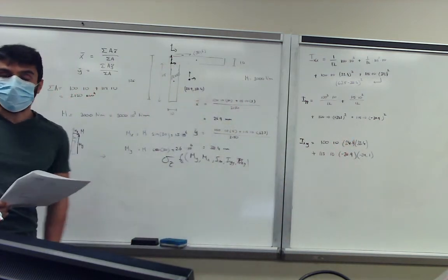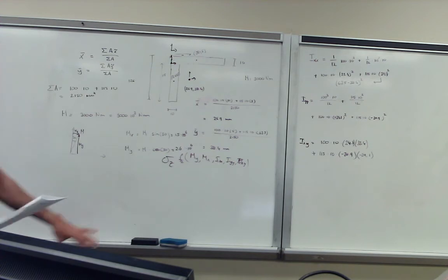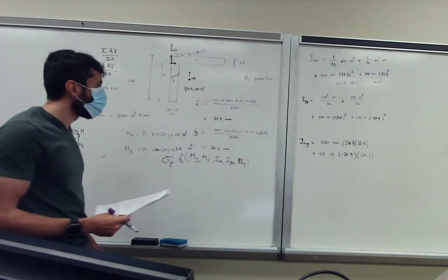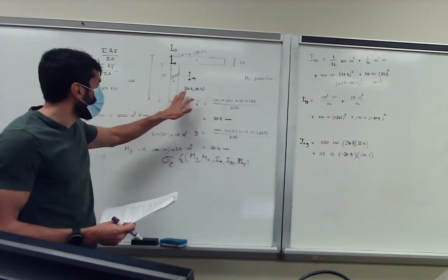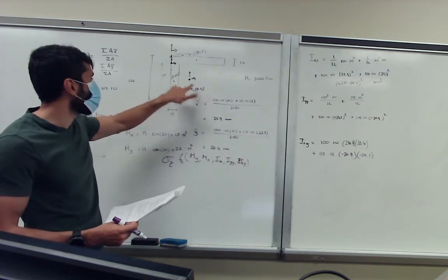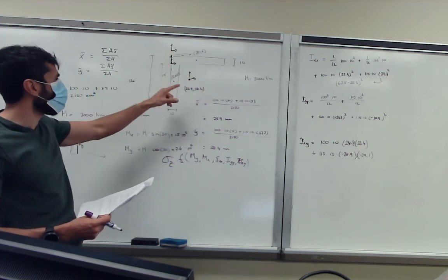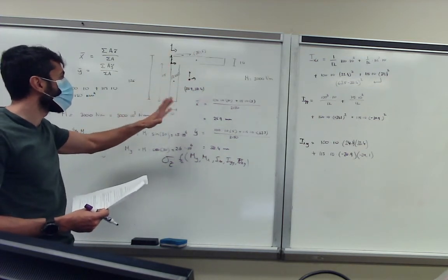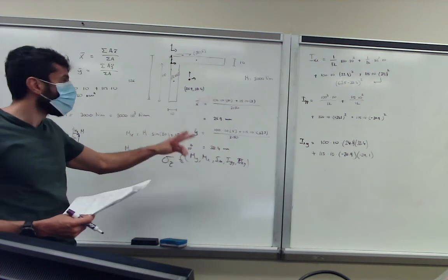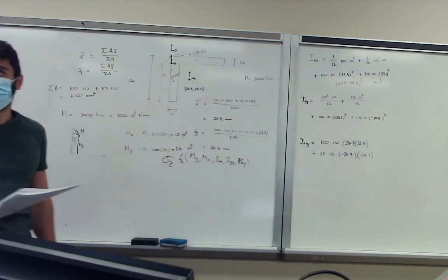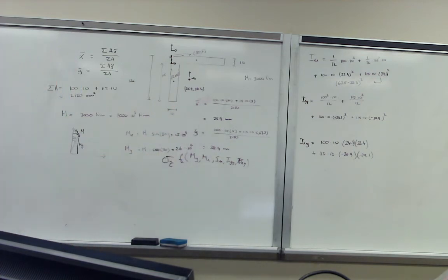So there are cases where the xy component is a negative number, if you don't take into account the correct centroidal axis and the distance towards it. I think using coordinates is easier than looking at distances and drawing lines. So you have to be careful with that. That's the only thing you have to worry about.